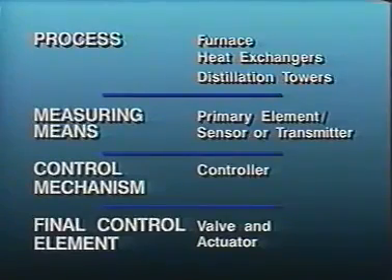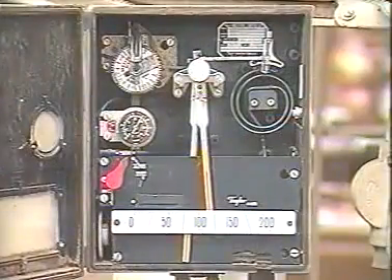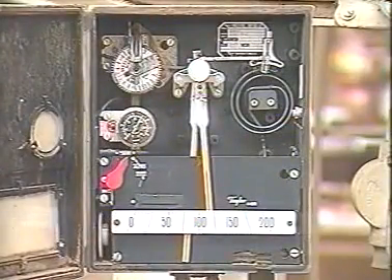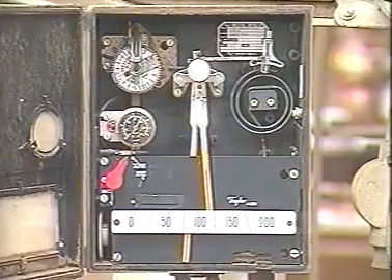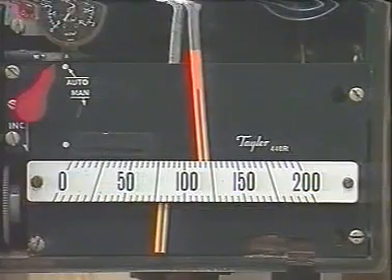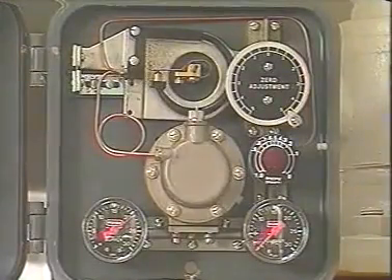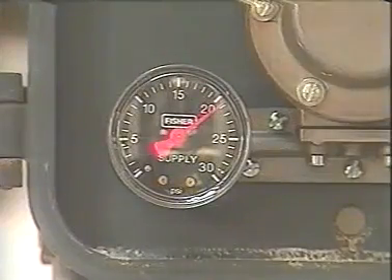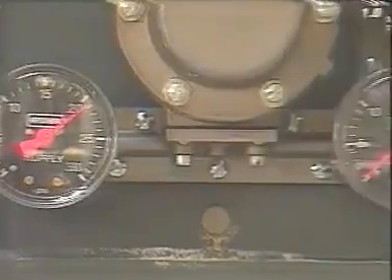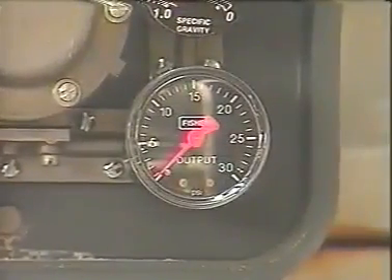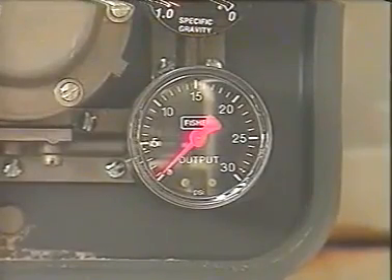In a control situation, we always need the 4 basic elements named on the left of this chart. The things named on the right perform the actual jobs in process plants. Almost any instrument in the 4 basic groups we identified can be connected to some type of indicator. For example, this field-mounted controller has a temperature indicating scale. The gauge at the bottom left of this controller tells us how much compressed air is supplied to the instrument, and the gauge at the bottom right tells us how much compressed air is being sent from the controller to the diaphragm actuator on a control valve.